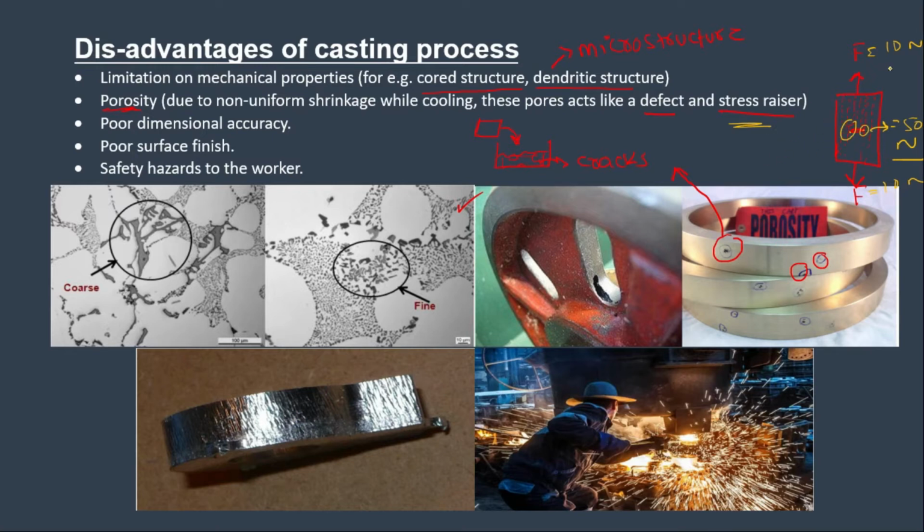As an engineer you are under the impression that you are only applying 10 Newton, but you don't know that because of the pore, the part deep inside is experiencing 50 Newton. So your part might fail without you anticipating the failure, because you calculated using the 10 Newton force, but you didn't know about the pore present deep inside, and the material failed.